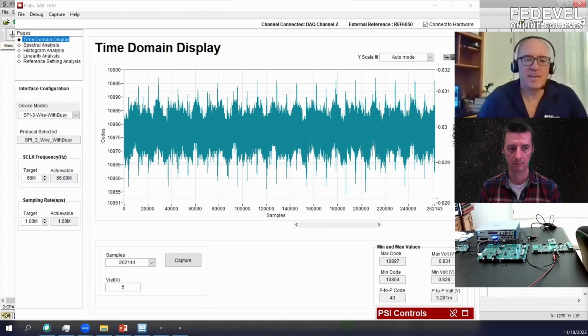So it can eliminate high frequency pickup, RF signals. And then, as I mentioned, some of our devices are a little bit more robust against noise. There's a spec in the data sheet that you can look up, EMIRR, or electromagnetic rejection ratio. If it has good rejection, then if you pick up some noise at very high frequencies, it'll eliminate or minimize it. And if the EMIRR is not as good, then maybe you might have to look for some other approach to minimize that noise.